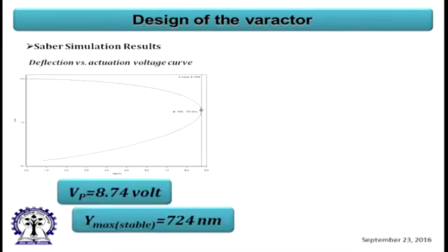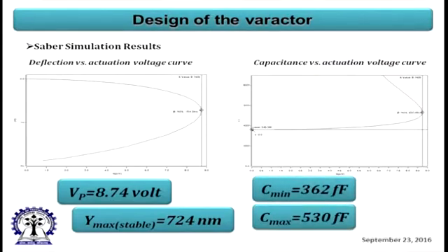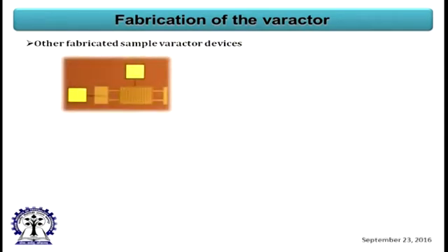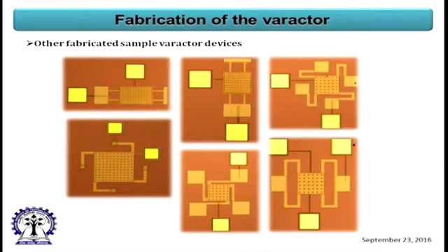If you make that structure, we found there is some voltage, and this is some kind of a varactor structure. You will find this is a meandering structure, this is the two-beam structure, and then we calculated it. This is the optical view of those MEMS varactors, which can replace the conventional chip varactor and so on.